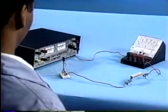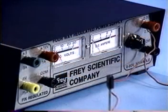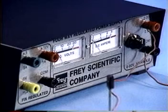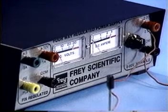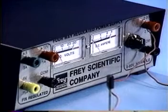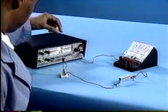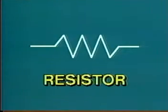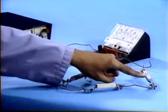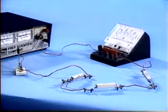To begin, build another DC circuit, but this time use a variable power supply as the power source. The reason for using the power supply is that it will enable you to more easily and accurately vary the amount of voltage in the circuit by simply adjusting the voltage control knob. In addition, fixed ceramic resistors will be used as the load in the circuit. They will be used because they are both inexpensive and a more precise resistor than a light bulb.